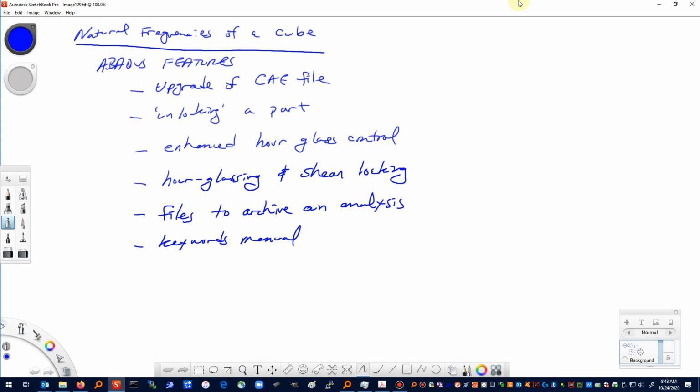One of the things that I always ask my students to do is to do something beyond what I've done in the video. And so some of my students have taken the beam and made it shorter and calculated natural frequencies. And one of the problems that some of the students encountered was something called hourglassing and shear locking. So I want to highlight this and show how you can recognize this and overcome this issue.